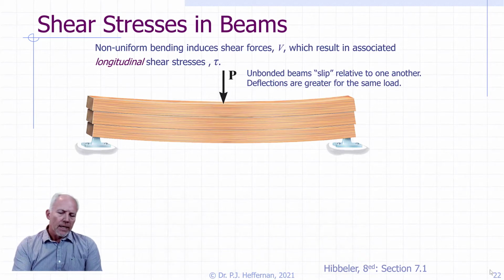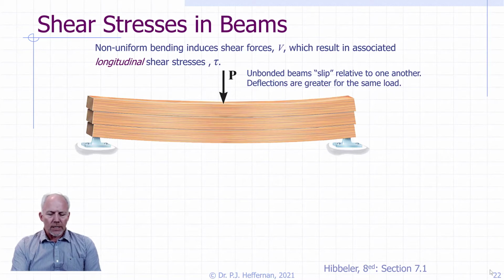I bring your attention back to when we looked at those in-plane shear stresses, very specifically our wooden shaft in torsion. Because of the in-plane nature of those shear stresses, when we twisted that shaft, we ended up introducing a longitudinal split between the fibers, because there's this weak plane between the fibers. Even though the shear stresses we were thinking of were occurring in this axis, the failure actually occurred in the longitudinal direction. And so I want you to think of that as we look at these beams.